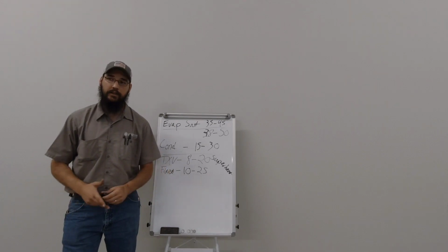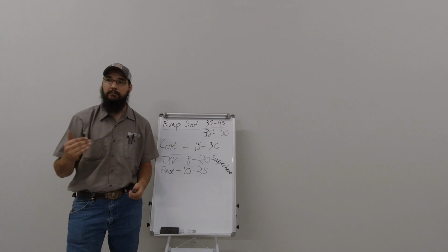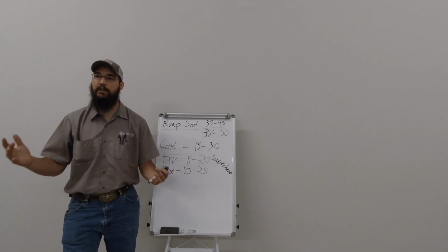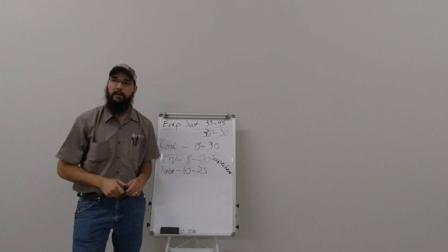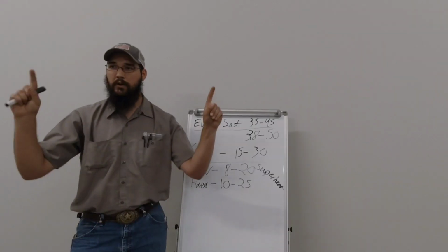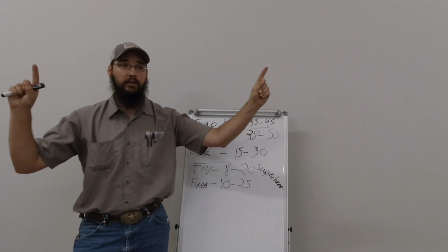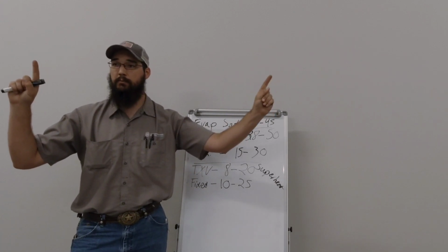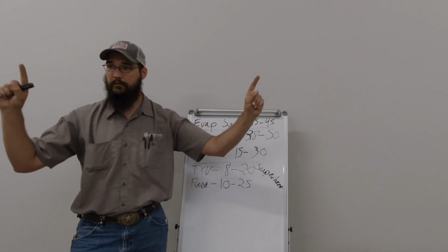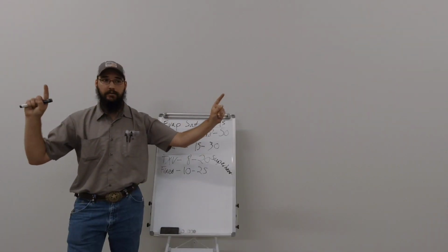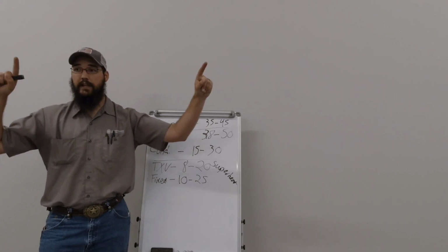So my expectation is I'm going to see that superheat come down, let's say no more than 10 degrees superheat, and see that saturation come back into the 40s. That's with 1 and 1, one on each circuit. I'm going to expect similar readings on circuit 2 with just one compressor. Now those circuits are splitting the load on that coil. Everything will balance out. But that's not the only way that those can run. So that's their normal staging.